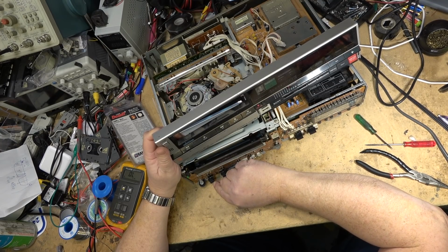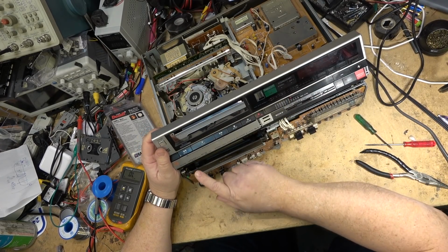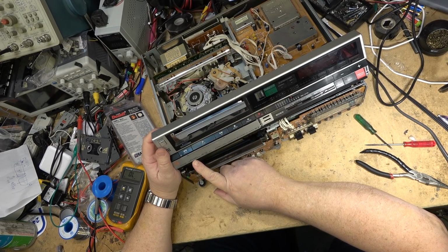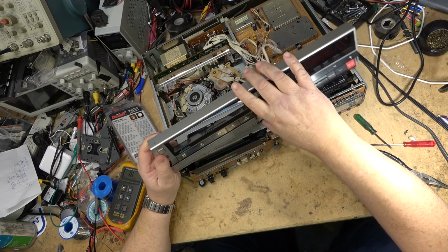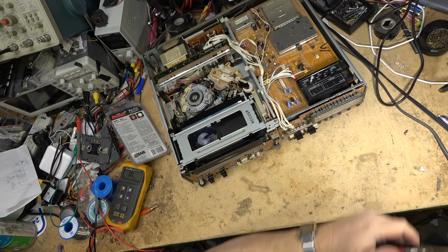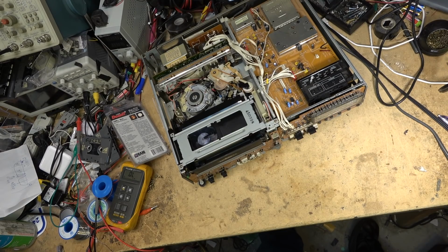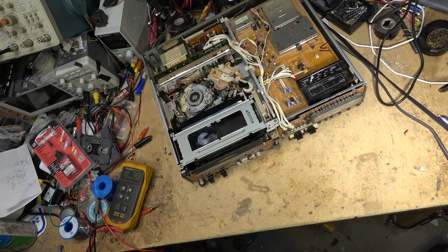Okay, that's more than likely what they've done on this switch. This switch, tuner, line PCM, and line audio. And I'll show you what it does, and I bet you that's what's happened with this tape that I've got here. This is not one of my tapes. This is a tape that was in one of these machines when I got it. More than likely, the dummies recorded it in line audio mode.